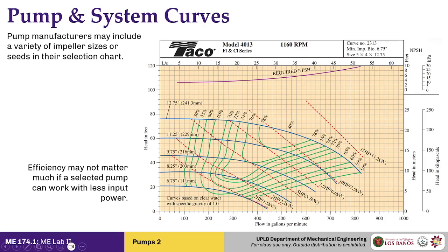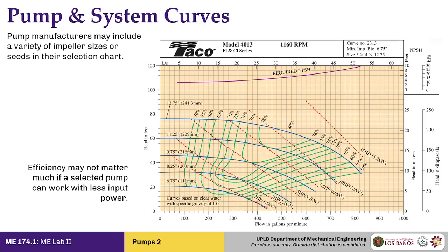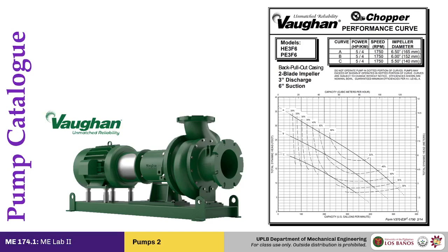So you might kind of see that for pumps at least, the discharge head is more important than the efficiency. But of course, you are the client, so you might have different priorities other than the standard. So here, the curve is actually from Sengel, one of the references. This one is essentially the same concept, but in a catalog that you can easily find on the internet.